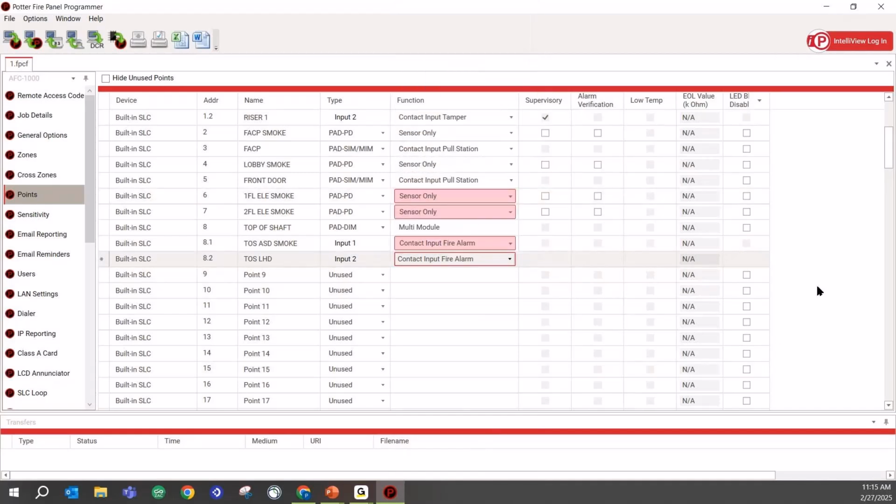So now I can put that control unit for that aspirating smoke detector in an easily accessible space, and then I've only got my tubing in the shaft. Linear heat detection, I can put that module and run that wire out through the top of the shaft, bring it back into that box, put my end-of-line resistor, and then all of that service and inspection, testing work, etc., takes place in that easily accessible space. So that'll take care of the top of shaft.